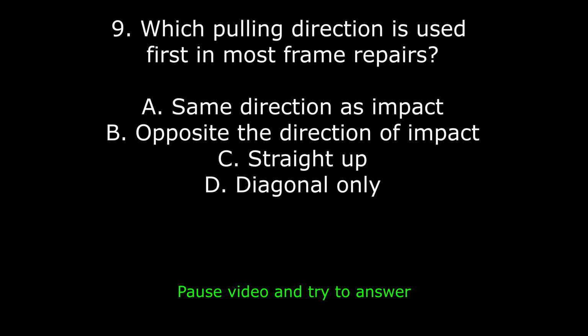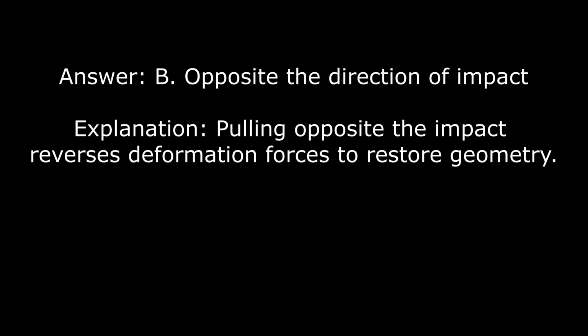9. Which pulling direction is used first in most frame repairs? A. Same direction as impact. B. Opposite the direction of impact. C. Straight up. D. Diagonal only. Answer: B. Opposite the direction of impact. Explanation: pulling opposite the impact reverses deformation forces to restore geometry.